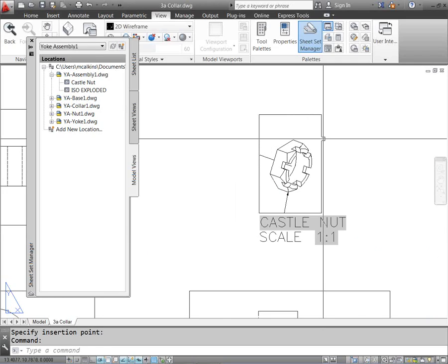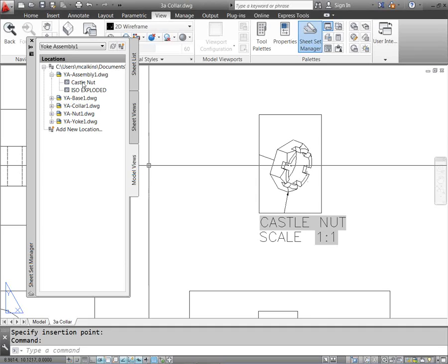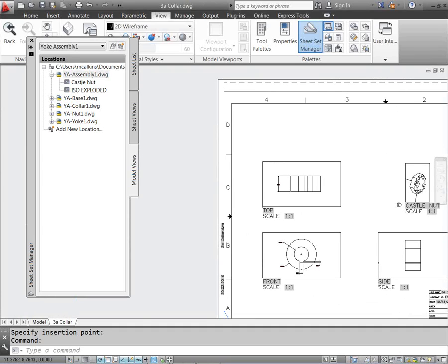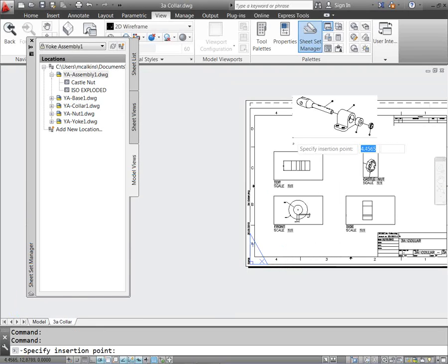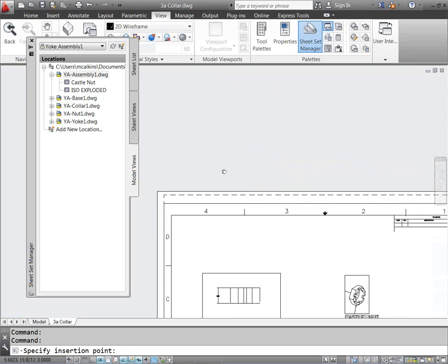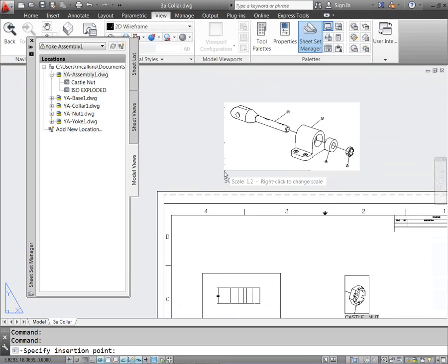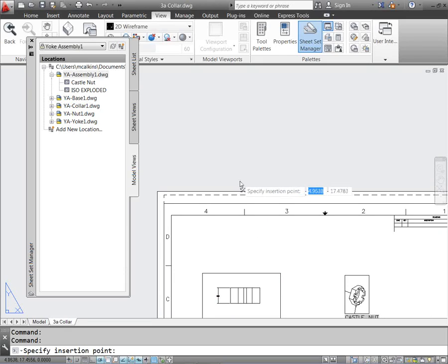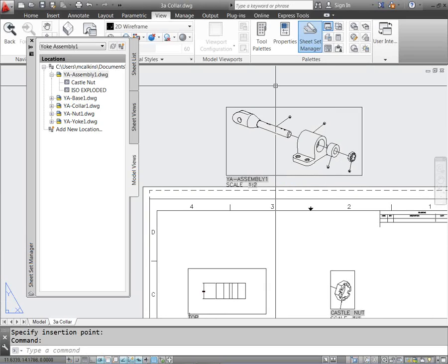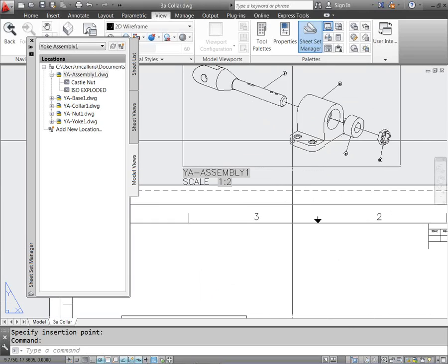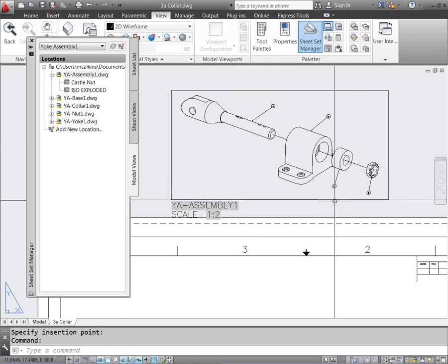And basically, the named view you created in the working file is going to be the shape and the boundary of your viewport when you place it onto the sheet. That's essentially what the named view is controlling. If you decide to drag the entire drawing, basically it's going to bring everything in model space across with your view. That might be acceptable. If you're a really clean drafter and you don't leave any kind of extra stuff floating out in space, that's fine. You can do that. Pull it through and it will pull in a nice clean boundary here around the extents of your model.